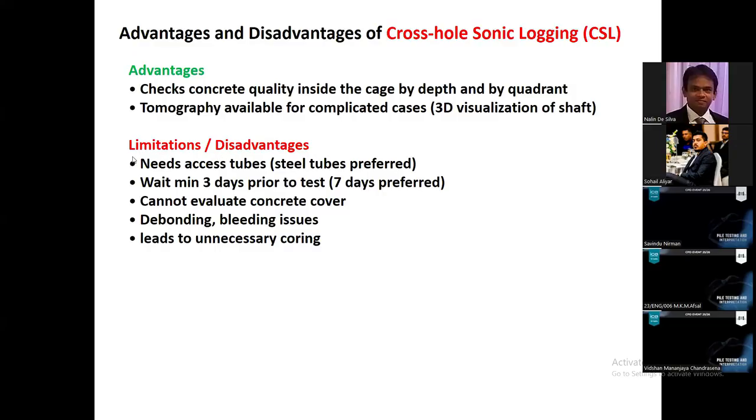And there are limitations or disadvantages. So we need the access tubes. And you have to wait for some time. Generally, we need to wait for about 7 days before conducting the PIT test or sonic logging test. At least 3 days of waiting time is needed until the concrete has sufficient strength.